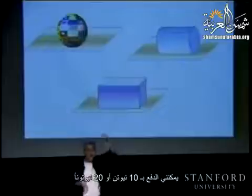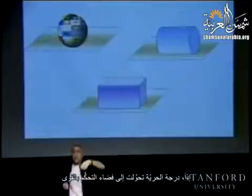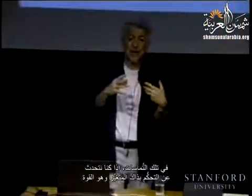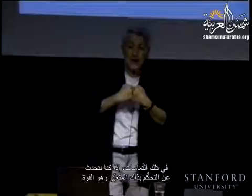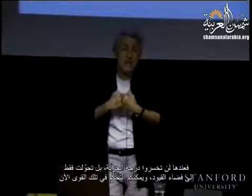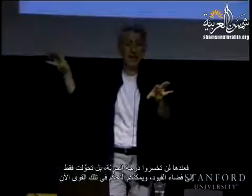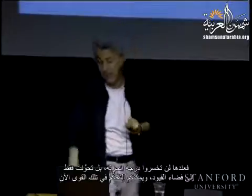Because if I'm pushing here or controlling this moment, I still can do it. I can push with 10 Newton, 20 Newton. So the degree of freedom just went to the space of force control. So in those contacts, if you are talking about controlling that variable, the force, then you didn't lose the degree of freedom. It went just into the constrained space, and you can control now that force.